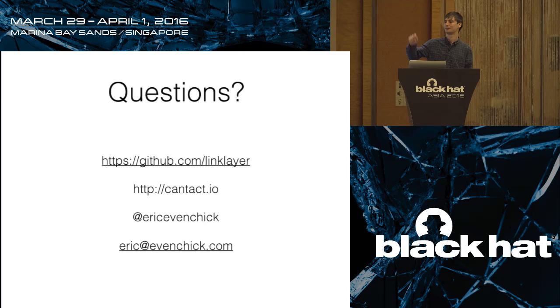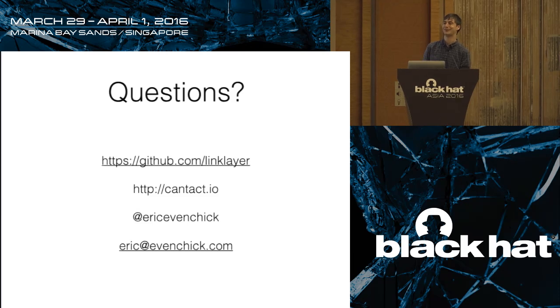Yes? Can you give some examples about the scripting ability? Yeah, so my favorite example of scripting is the silly one of doing a denial of service. I didn't talk about the electrical characteristics of CAN, but really simply, low IDs have priority and they win. So if you send the message with ID 0 really, really fast, you will basically shut down most cars. That's one really fun one that is like 3 lines of code.